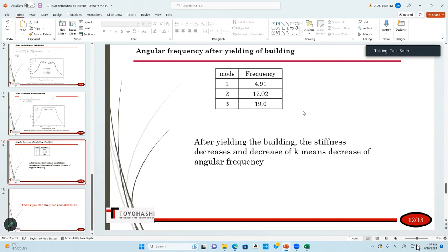Actually, it's not easy. I tried, but it's not easy. Yeah, because there are many reasons. For example, in a lumped mass model, you have a lumped mass and the TMD is connected by a rigid floor. And when you apply wind, we want to apply wind only to the main building, not the TMD. But it's not so easy.